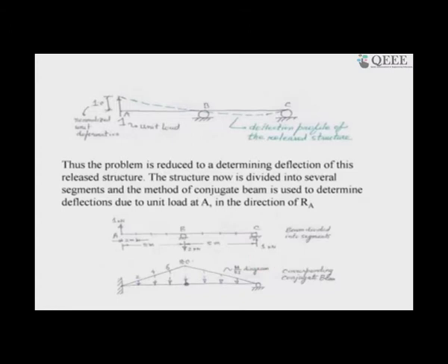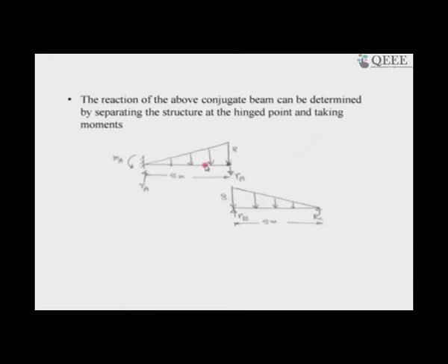So, my entire work is now to find the shear and bending moment in the conjugate beam, and I will find the slope and deflection. It is the bending moment in the conjugate beam which will give me the deflection. This loading is the M by EI diagram of the actual loading. I have now drawn the free body and found the reaction of the conjugate beam from the M by EI diagram of the real beam, and I am fully ready to determine the bending moment at a section. On the first day I told you how to find the bending moment at a section.